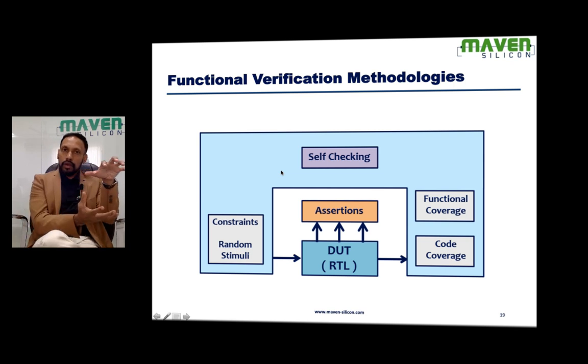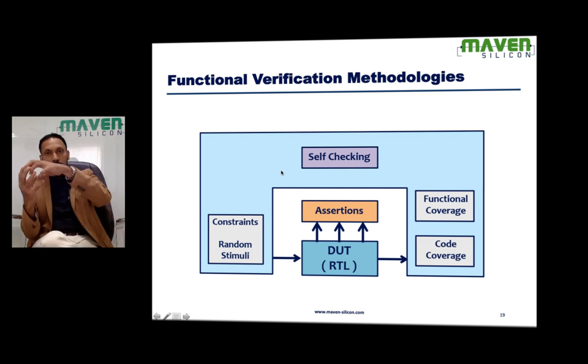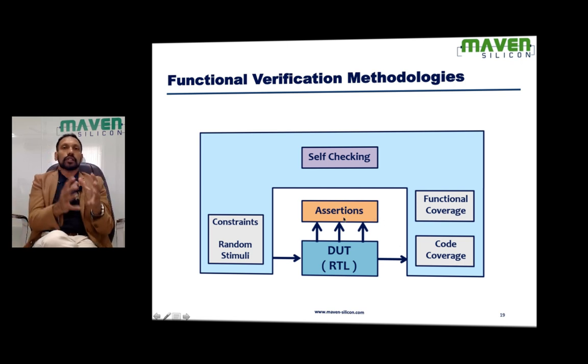So we try to verify the design before simulation through linting, and we capture all the details as part of the verification plan. We implement Testbench. We try to generate different kinds of coverage values. Look at here, functional coverage and code coverage. And we also implement assertions. It's called assertion-based verification. We need to look at different things like data comparison and protocol validation. Usually we implement scoreboard for the data comparison, but when it comes to protocol validation, we prefer assertions.